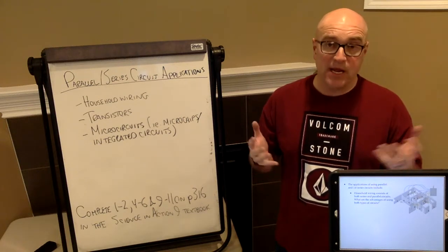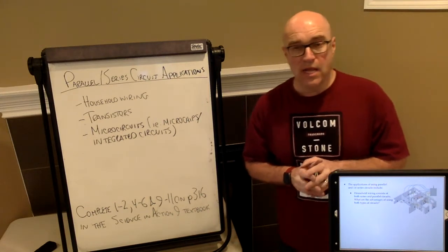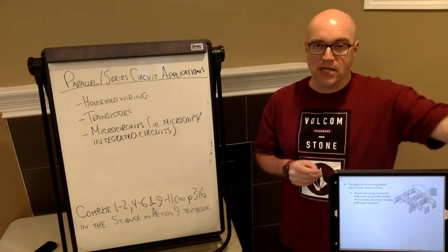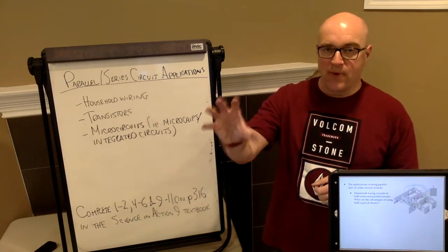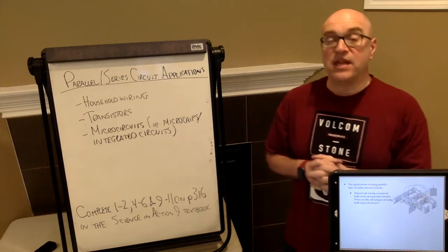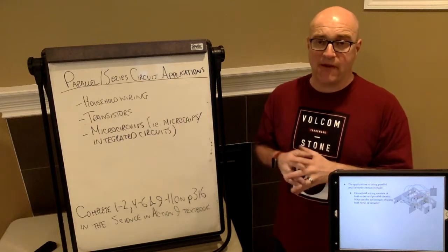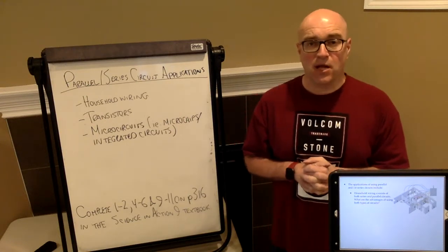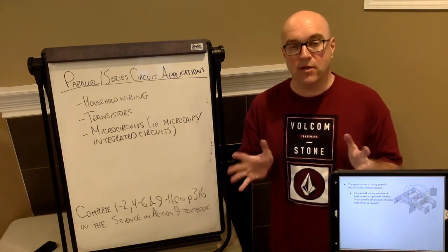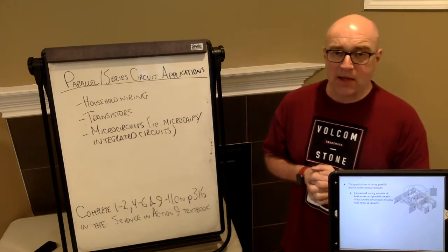But there would be situations where we want parallel wiring, where we want to be able to separate lights. For example, in the kitchen, I don't want all my lights to go on at once. I just maybe want my nook light to go on, or my light over my island, or my under counter lighting. The analogy would be if I had a series circuit in my entire house, then I would flick one switch and all the lights and everything would come on in my house at the same time, which doesn't make a lot of sense because that's a lot of extra power that you're drawing to light your entire home all at once. So houses, generally speaking, have a lot of parallel wiring in them to allow you to light each room separately.